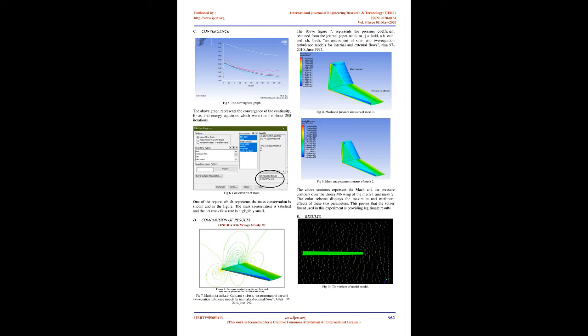The CFD simulations use the flow field conditions given in Table 1, corresponding to a Reynolds number of 11.72 million based on the mean aerodynamic chord of 0.64607 meters. The M6 wing geometry dimensions are scaled down to 1/3 of the original geometry to reduce the computational time while performing the analysis.